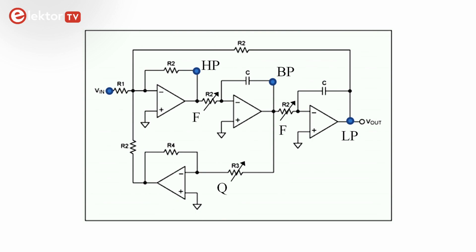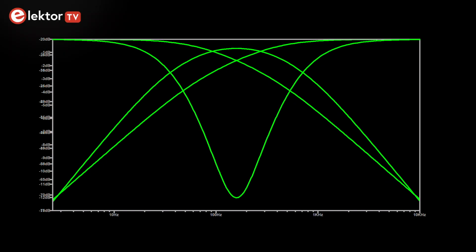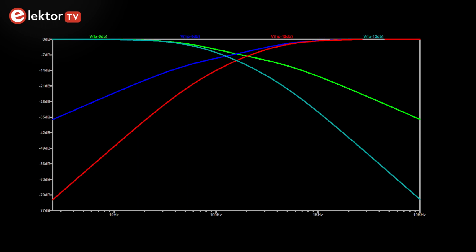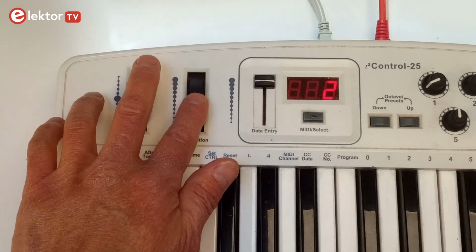The output of the noise generator is passed through a filter. Several types are available: low pass, band pass, high pass and band reject or notch. The low pass and high pass filters both have 2 slopes, 6 dB per octave or first order and 12 dB per octave or second order. The cutoff frequency is adjustable, but not the quality or Q factor.